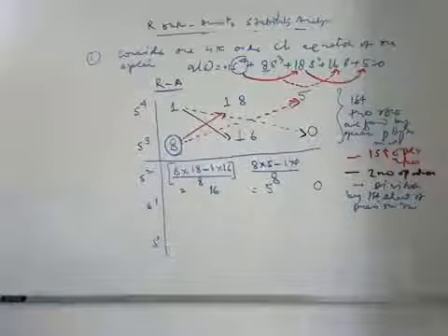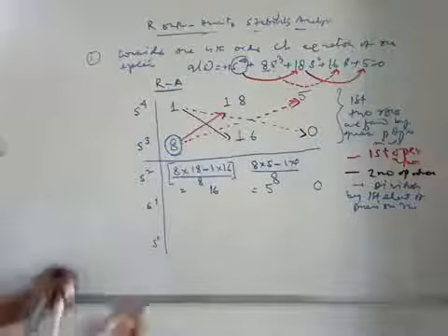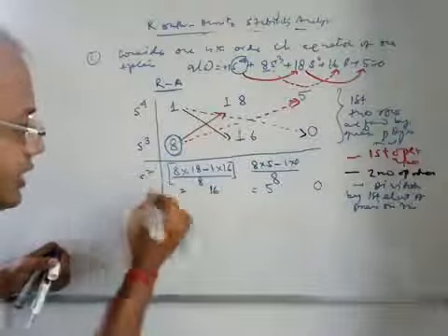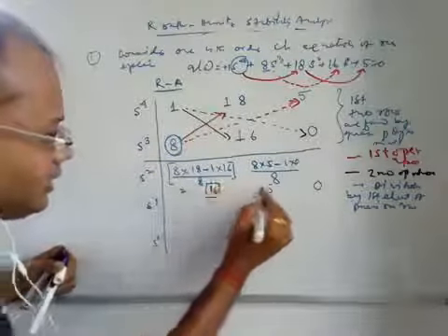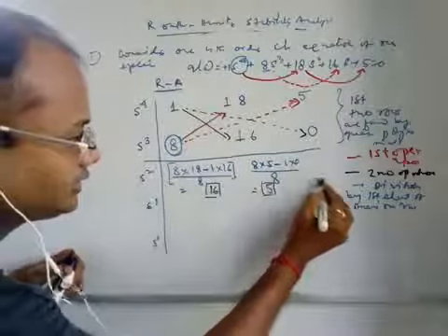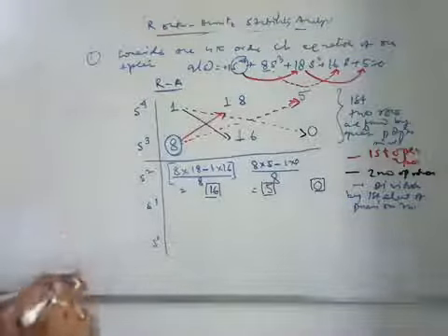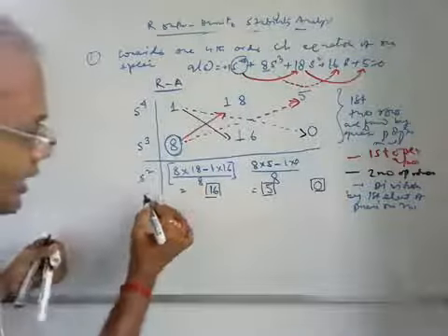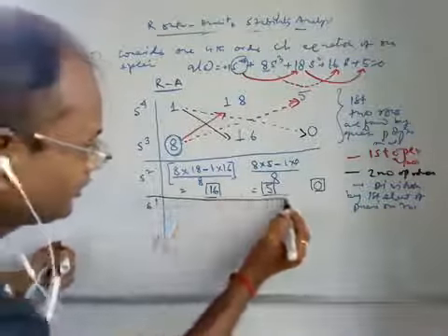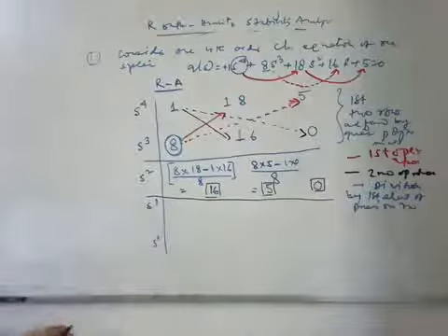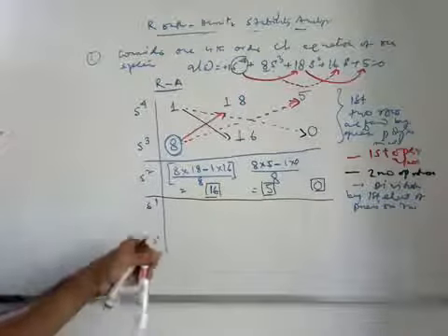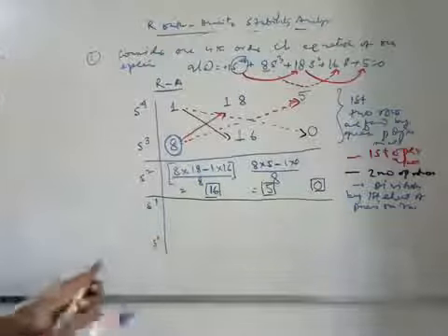So in the previous row, what you have obtained is the coefficient of s square: you get 16, 5 and 0, right? Once the s square row is formed, next you have to form the row consisting of the coefficients of s to the power 1. How can it be formed?